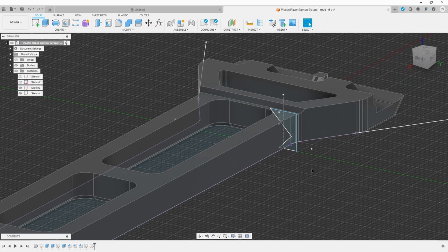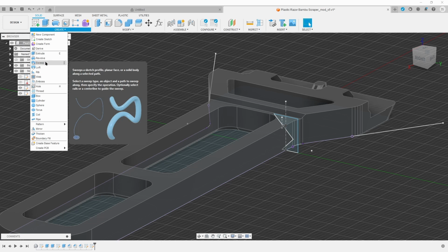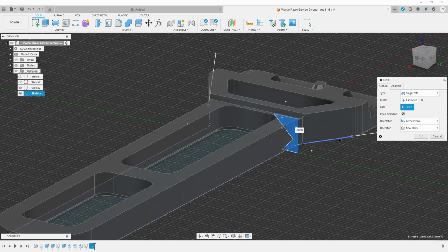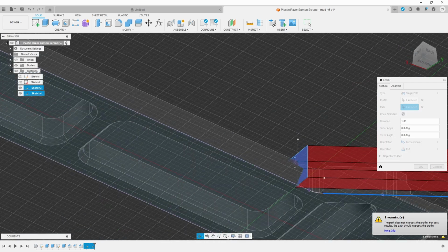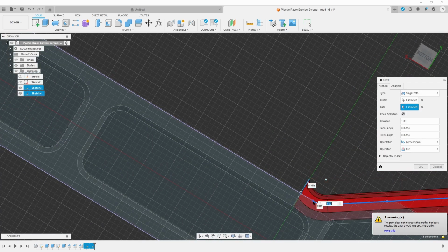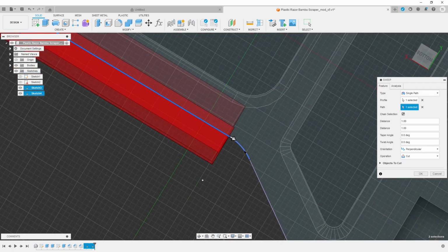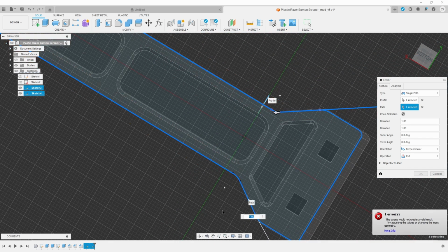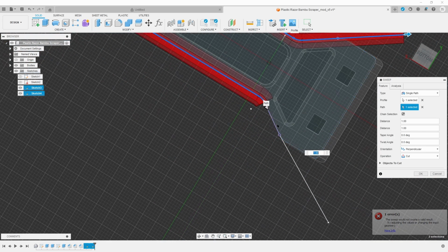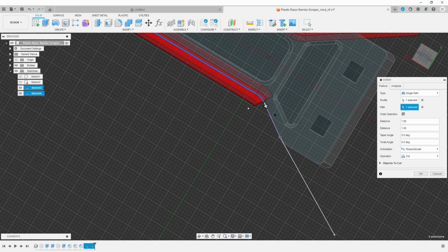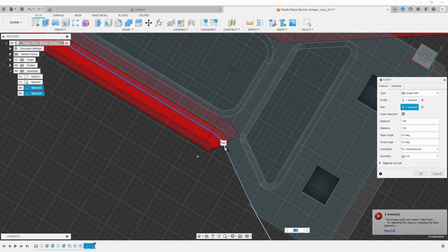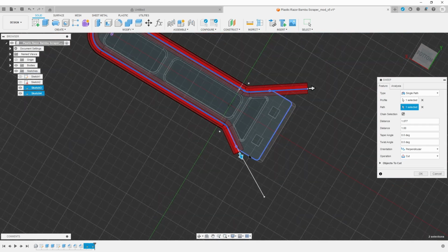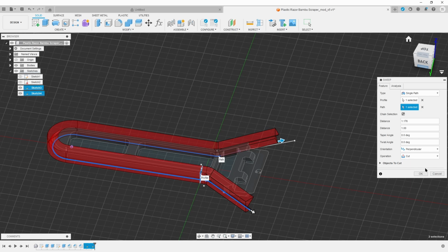So in order to create this chamfer, what we're doing is we're using the sweep tool. And so we're sweeping this path that I created previously in a previous sketch. When I try to select the last piece, it keeps wanting to select the whole curve, which creates a problem. So I ultimately grabbed the little ear and pulled it out, which is another way of achieving the same thing that I was trying to achieve in this particular part.